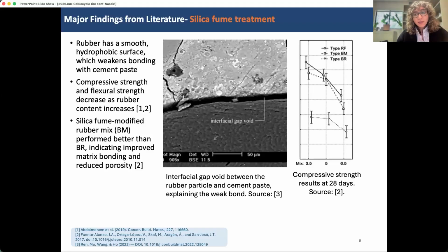And generally, this material is not compatible with a mineral-based, calcium silica-based form of material, which is a cementitious environment, right? So from the literature, if we look at some of the microscopic images of the interface between a cementitious system up top, the lighter gray, and then the rubber, you can see a gap. The gap is clear. And this is not unexpected.